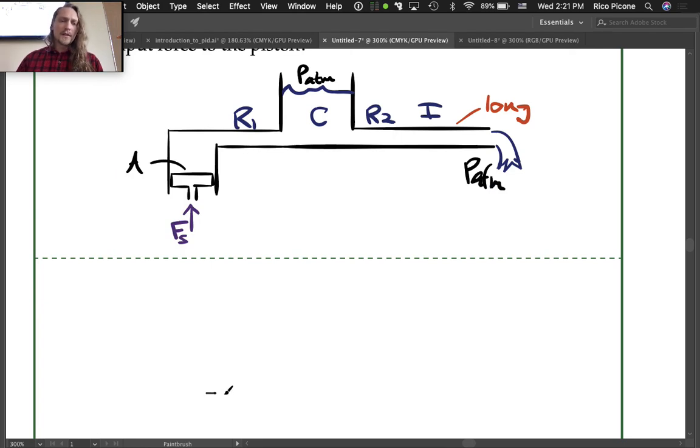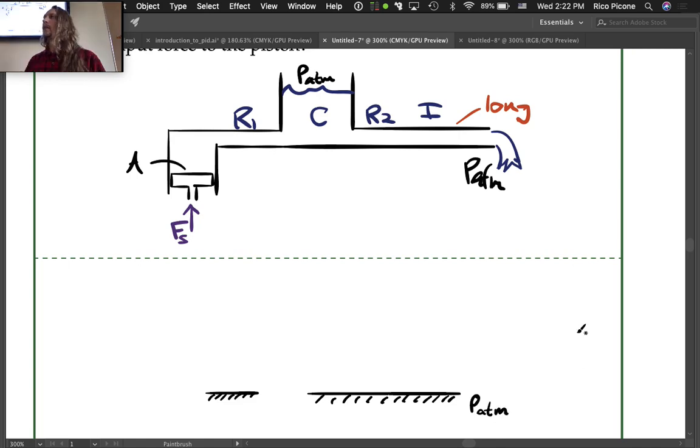On the mechanical side, let's draw a reference. And on the fluid side, let's draw a reference. The reference on the fluid side is typically going to be atmospheric pressure, and it makes sense to use that here. The reference on the mechanical side could be, for instance, zero velocity. It just needs to be some constant velocity, right? An inertial reference frame. It's the important thing. And then we have a mechanical node, which is going to be the distinct translational velocity of this piston.